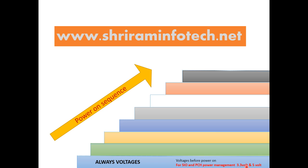That voltage is supposed to be 3 volt. Before power on, you should get 3.3 and 5 volt at the always section. Okay, so this is the first step. Before turning on the laptop, before turning on the switch, you should get 3 volt on any laptop, and this voltage is called the always voltage.